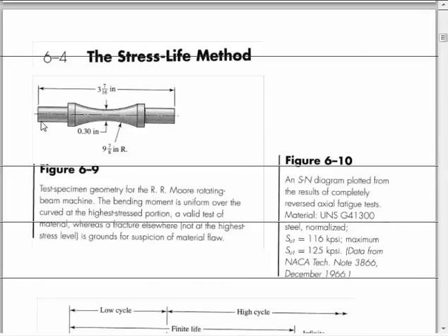We talked about the rotating beam specimen being a very specially made test specimen, and it is called the rotating beam because we will support this as a cantilever at one end, and we will place a moment at the other end, and that'll cause a bending stress. At the same time we're loading it, we're going to rotate it so that the stress goes from high to zero to negative, back to zero, back to high on every piece of material in here. As the beam rotates, we'll go from positive stress to negative stress. So here's where our fatigue data will come from.